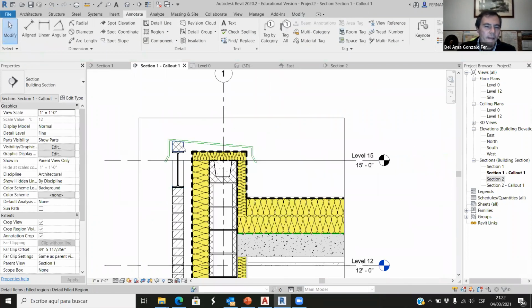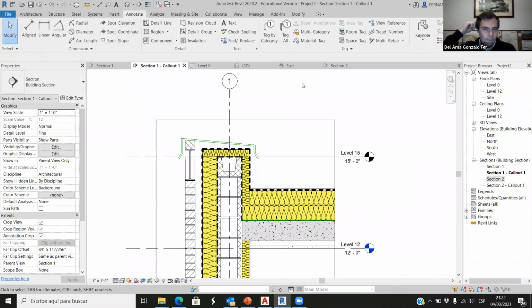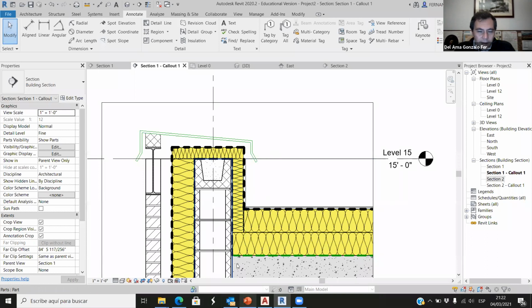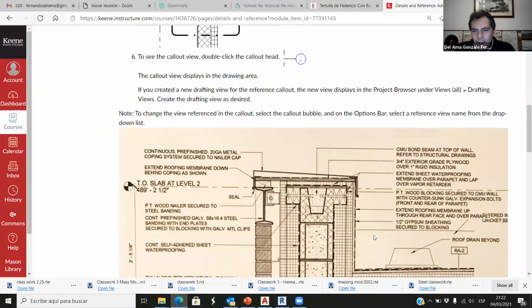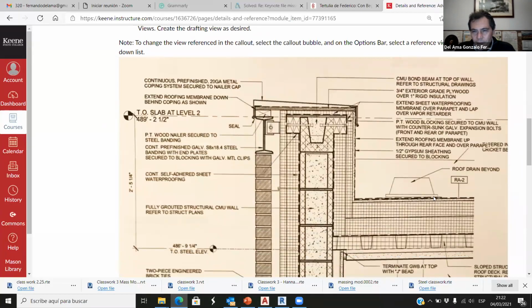Okay, with a hatch here, because this is something we have to nail this element to, and we have to protect everything against the rain. Okay. Anyway, there is something that we have to understand today as well. Here, these corners, sometimes we have a double waterproofing layer.